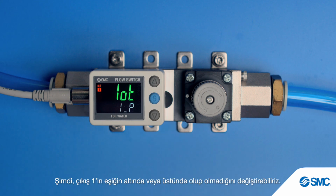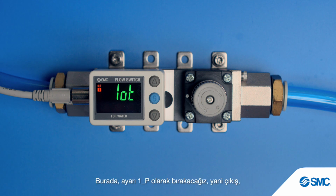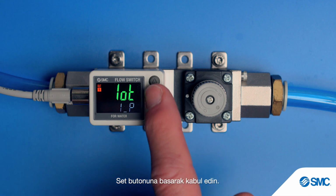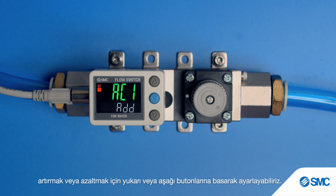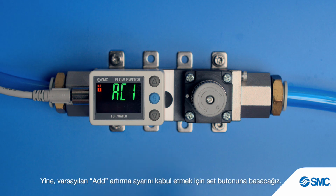Now we can change the type, if output 1 is on either below or above the threshold. Here we'll leave the setting as 1_P, meaning the output is on when the accumulated flow is measured above the set point. Press the set button to accept. Now we can set the PF3W to increase or decrease the accumulated flow as fluid passes through the device by pressing the up or down buttons. Again, we'll press the set button to accept the default add, increase setting.